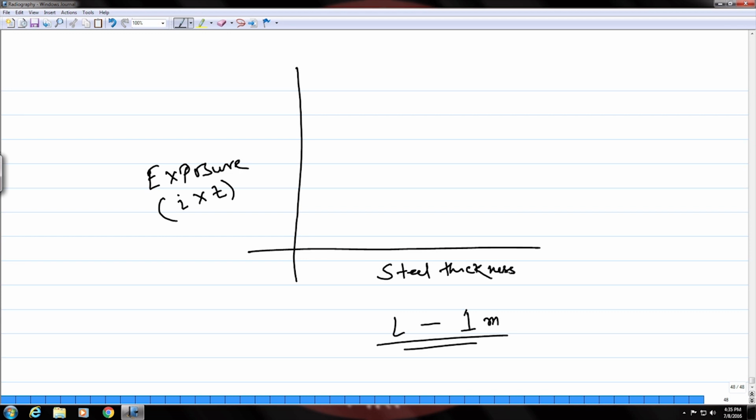Okay. So, it can be done for example, on a steel sample for a fixed sample to source distance of 1 meter, and then you vary the thickness and obtain the data, and when you plot the data at different tube voltages, this kind of curves will be obtained.